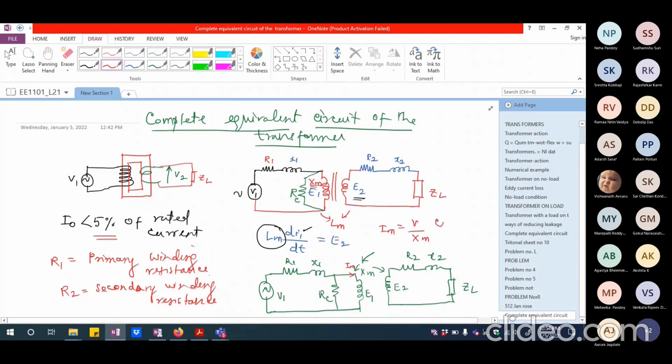The same way, core loss is generally proportional to about B square or B power 1.8. That's what they say normally. Okay, it is an empirical relationship. It is not really derived theoretically, it is derived experimentally. That is the reason why we call that an empirical relationship. Core loss is roughly proportional to B square.